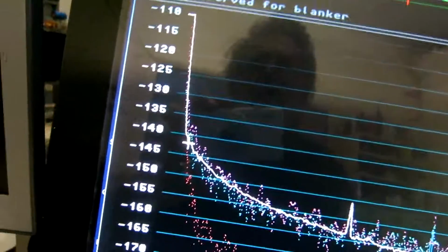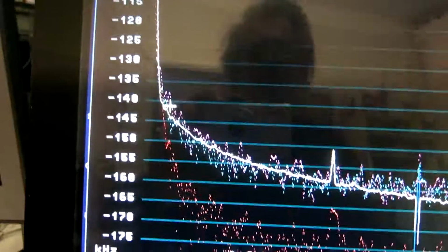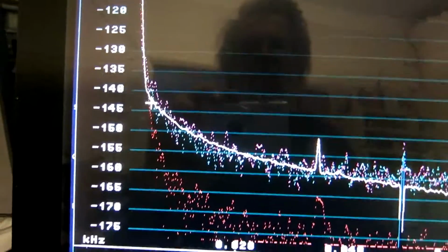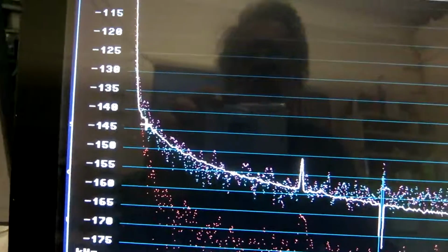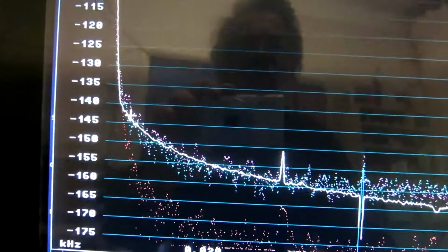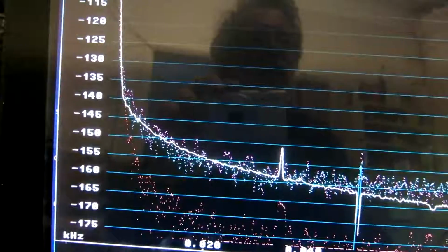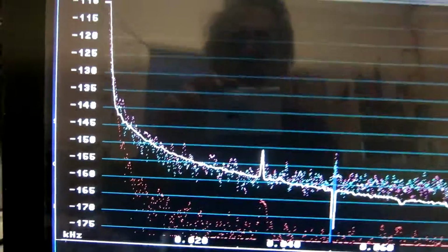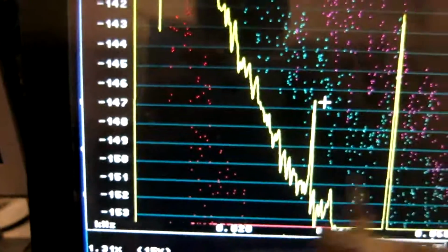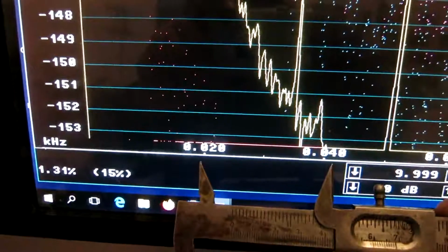This will be a later study when I have fixed, if I can do that, the phase detector or the PLL between the two oscillators, or the coupling between them, or whatever causes the error on the phase noise measurement below 10 Hertz. I do the evaluation like this. Here is 20 Hertz.